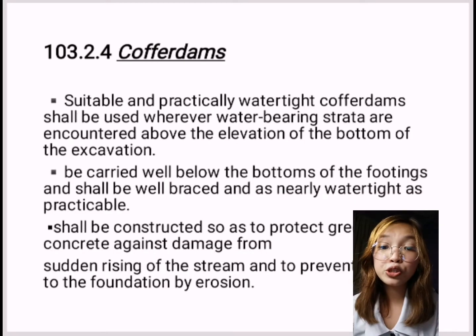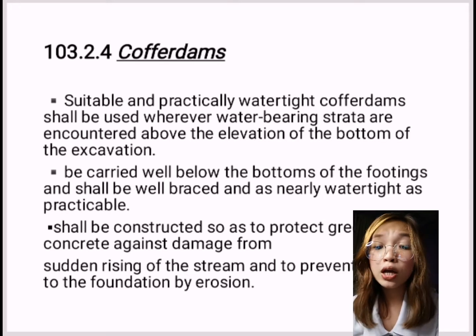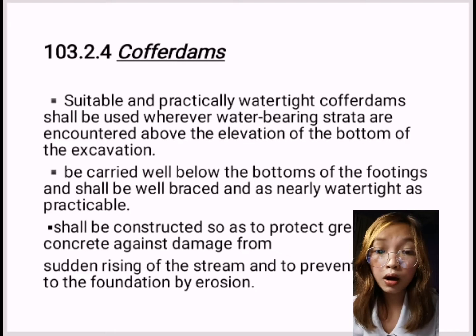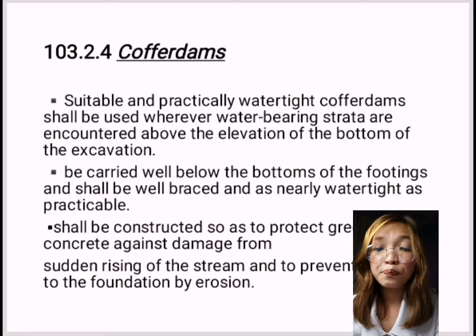So next, let's proceed to item 103.2.4. So it is the cofferdams. So suitable and practically watertight cofferdams shall be used wherever water-bearing strata are encountered above the elevation of the bottom of the excavation.